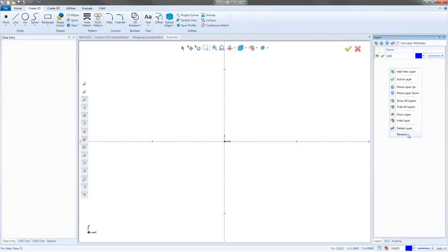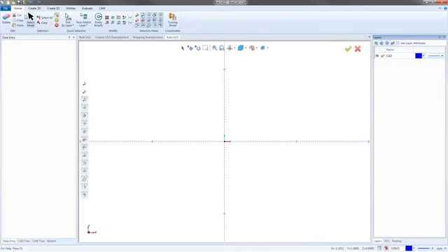So if that happens, you just have to open up the layer. And what I do is turn all the other layers off except the one I'm trying to delete. And then on the home tab here, you can just say, I want to go into select mode. I want to pick all, and then just hit delete on your keyboard and then trash it, because that should usually go. Great, Nick. I'm glad you got sound finally.